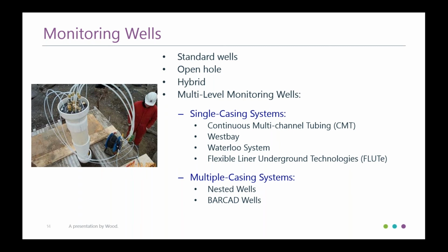But it's always, I think, better to put a well in if you have that option. And I think people leave these open sometimes for thinking about what they're going to do in remediation as extraction wells or maybe injection wells. And then multi-level monitoring wells. Not only can you do nested wells, but there are several systems out there that are single casing systems that will give you some information as well.